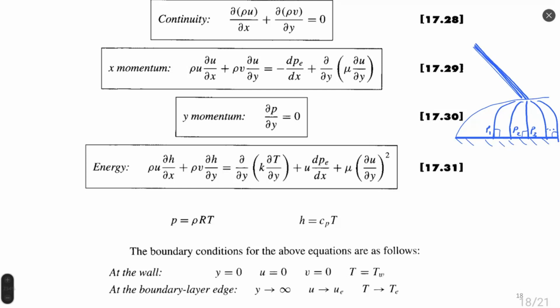Okay, if we make same simulation but for inviscid flow, we will see that pressure lines will be not normal, will be inclined. Something like I will try to show you. Okay, this is our shock wave. This is the wall. This is our shock wave. A lot of lines because it hits the surface. And then it reflects from the surface.